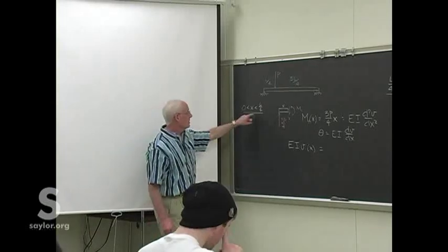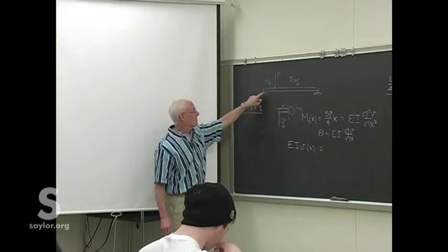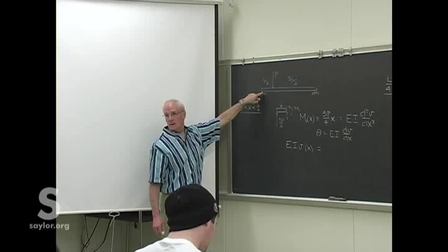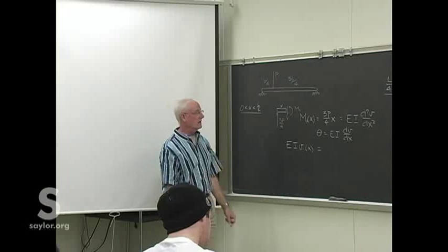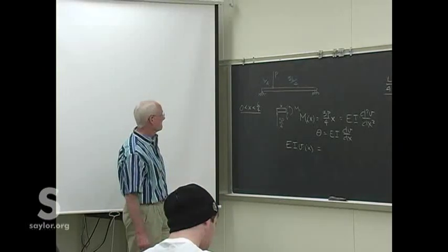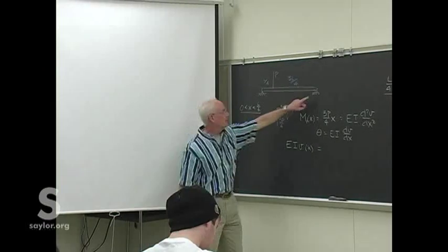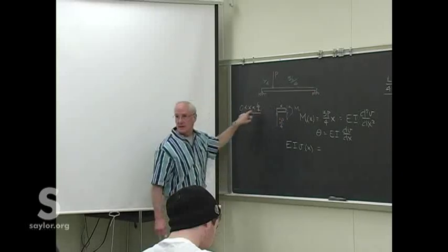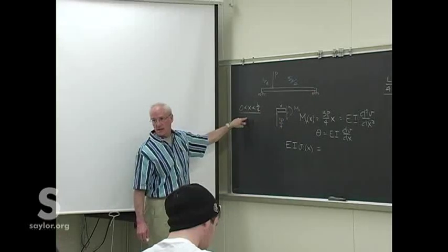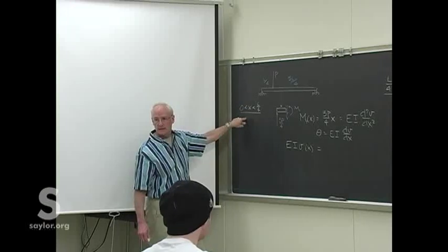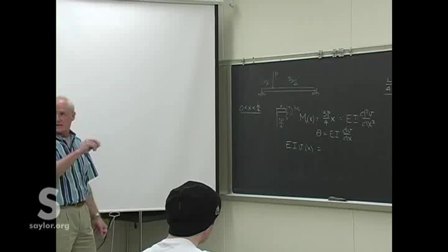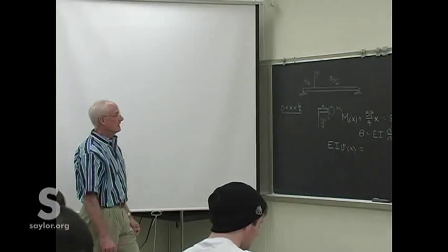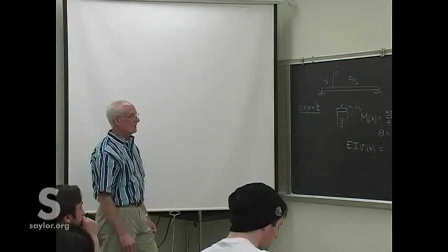Well, you can do one boundary condition, because you know that there'll be no deflection of the beam at this support. So you can take care of one of the boundary conditions. You can't apply the other side because this function doesn't go to the other side. It only goes up to the load P. Then we're going to need another function there. What we have is two elastic curves, one describing each side of the load.